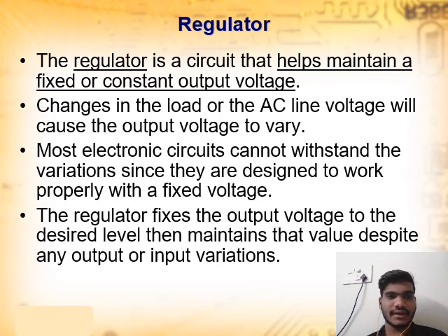The regulator is a circuit that helps maintain a fixed or constant output voltage. Changes in the load or the AC line voltage will cause the output voltage to vary. Most electronic circuits cannot withstand the variation since they are designed to work properly with a fixed voltage.